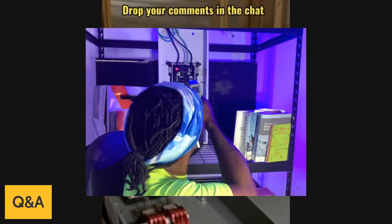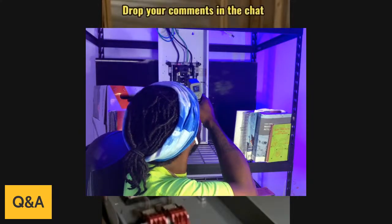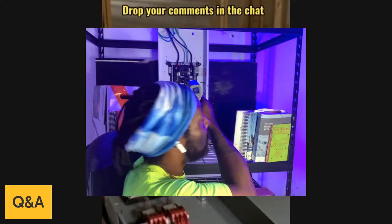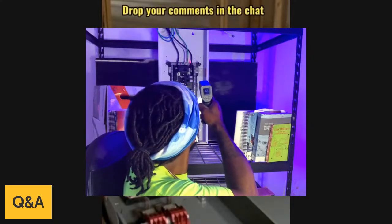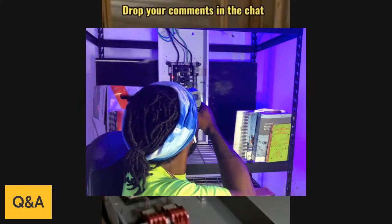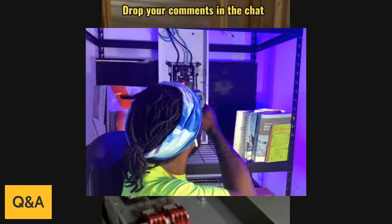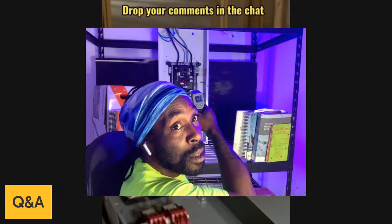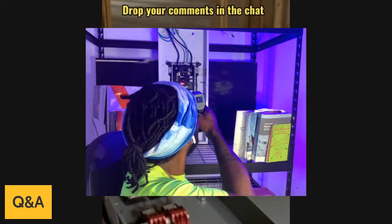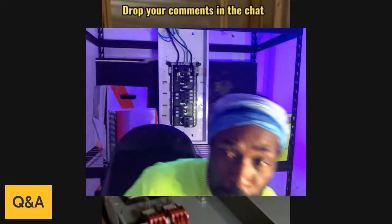So basically, that's how you would test to see if your wires will be overheating. You just slide the right dot on here, and it's going to give you the temperature on it. So with the lugs also, with the neutral bars also, same process. You can also go into here, that's where your breakers are going to be landing. So pointing this will basically give you the temperature pretty much. And that's how you go about it.